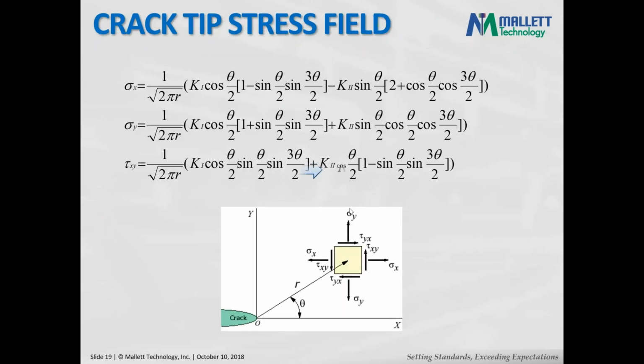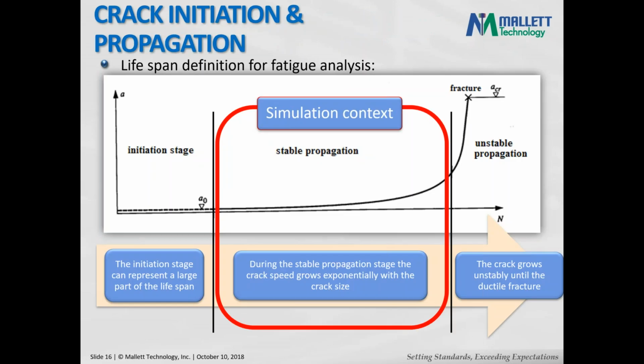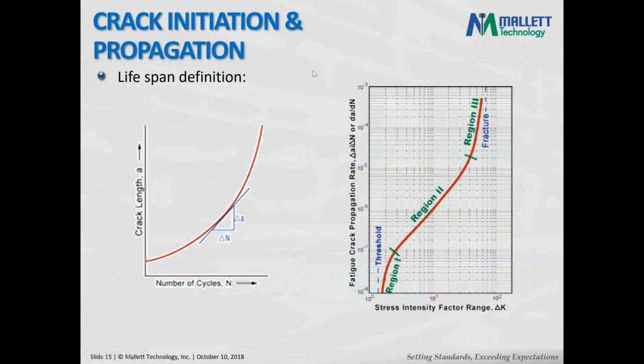If there's not going to be an imminent fracture, then what do we do? Then we go back to these curves here, and we compare what we are seeing to the threshold value. The threshold value is, say, of the order of 2 KSI square root of an inch. That's typically a good number for the threshold value, 2 KSI square root of an inch.